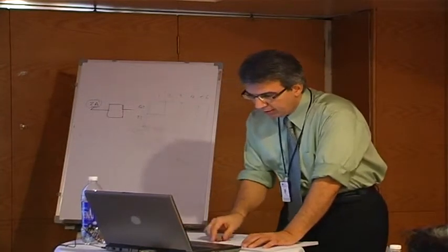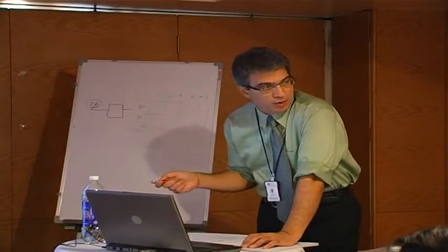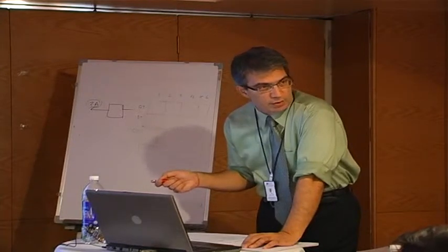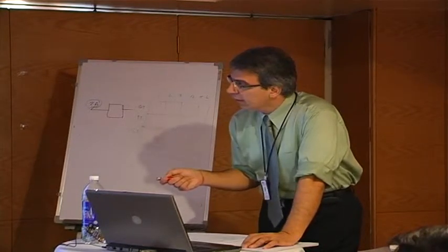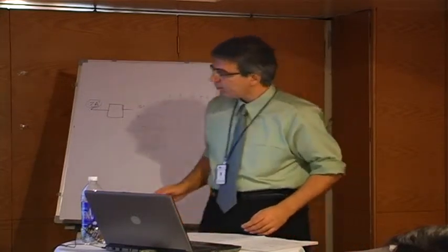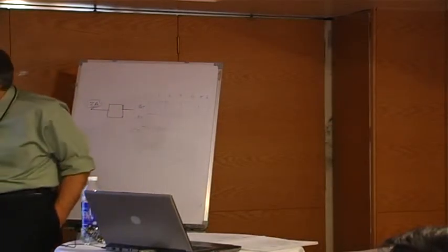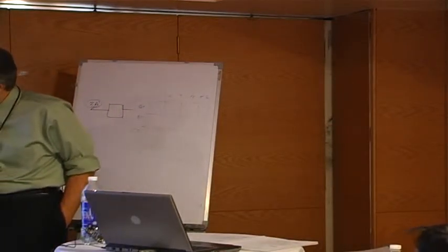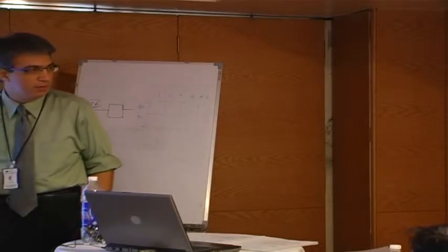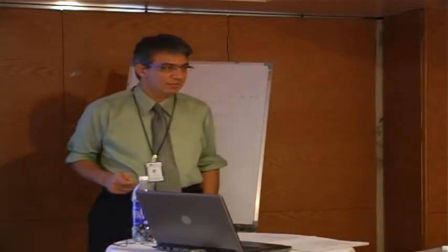Now this block here is what we call an ABM block. It's the analog behavior model block in PSpice. And what we have done, if you remember, these were the sources we used for a similar one to generate the motor model. The same thing we are using for the generator.